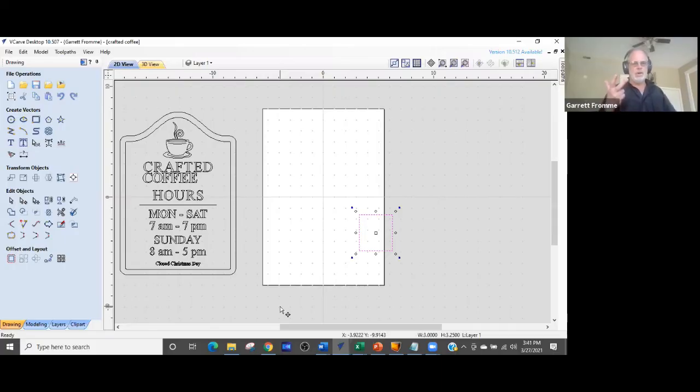And then you go and move it and set a new zero over the center of your part or at the corner of your part. And you're not changing the home position. You are telling the software, I am referencing the home position by this X, Y, and Z distance.